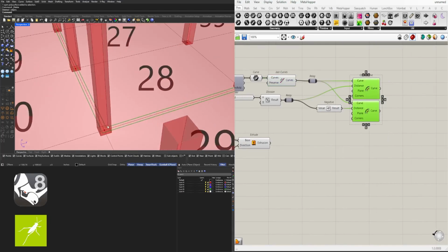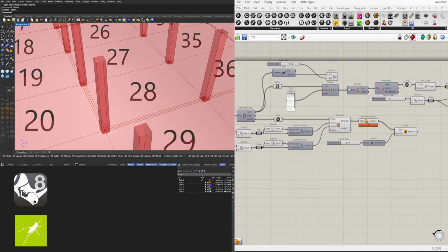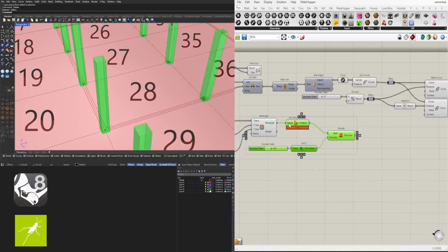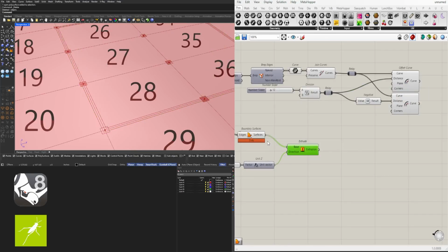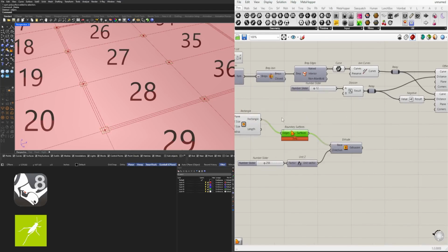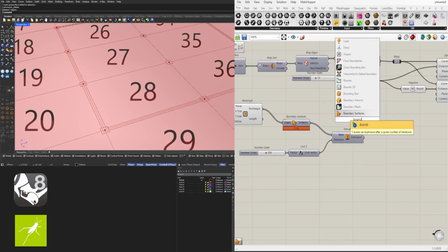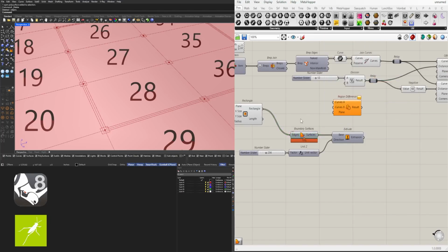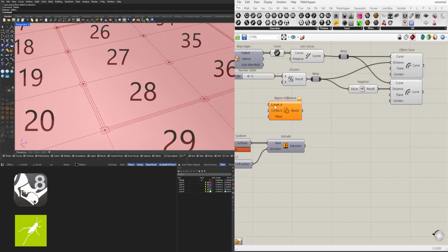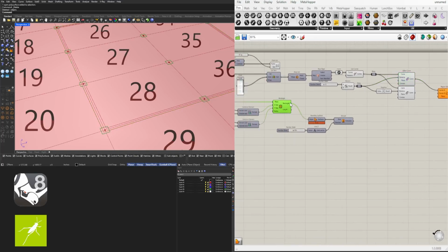So we can create a surface here, extrude it and subtract it from the columns, or using this technique, which is going to be subtracting. So I'll hide columns here. We're going to subtract the rectangle from these 2 polylines. So I'll go here to boundary or region difference. Region A is going to be what we keep, and B is what we subtract. So we're going to keep curves A, the outside, and subtract the column.